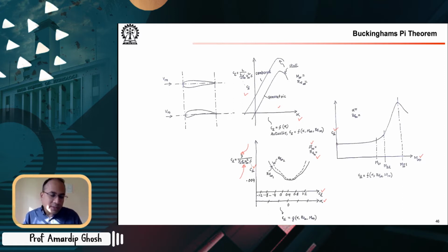And we will see that things like Mach number, Reynolds number, Prandtl number, these non-dimensional groups come out from that treatment of the governing equations. On the other hand, Buckingham's Pi theorem is a simpler approach of collecting these non-dimensionalized groups which are of importance to a physical problem, but not necessarily do these non-dimensional groups have the connotation of physically relevant parameters.